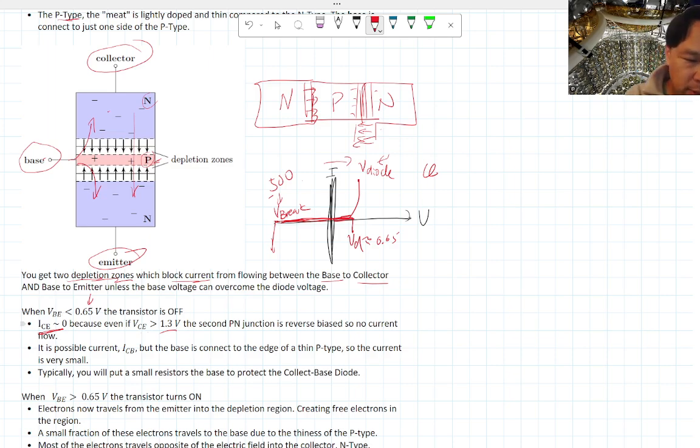The turn-on voltage for the transistor we'll be using is about 0.65, and let's say we have 12 volts on the collector, just to keep it constant. Usually that's denoted as VCC. And then the emitter, let's just tie that to ground.